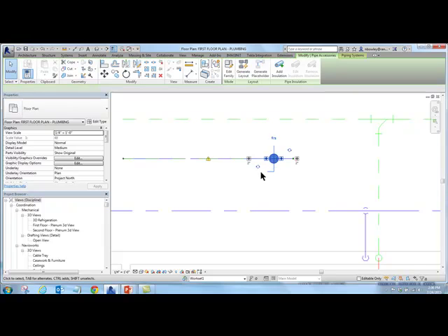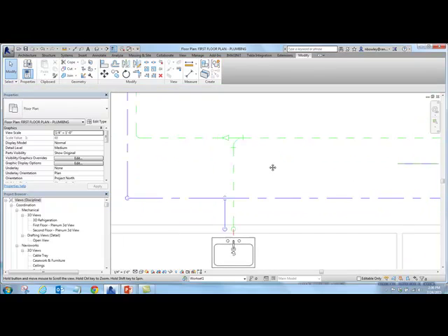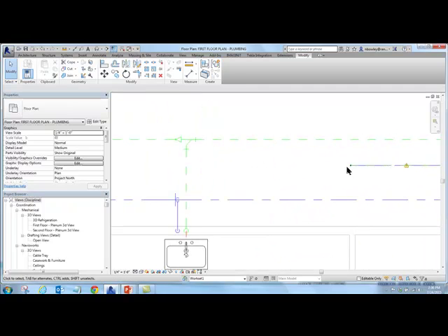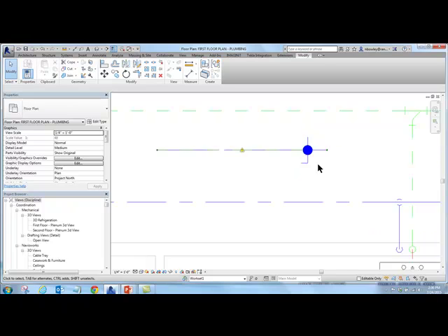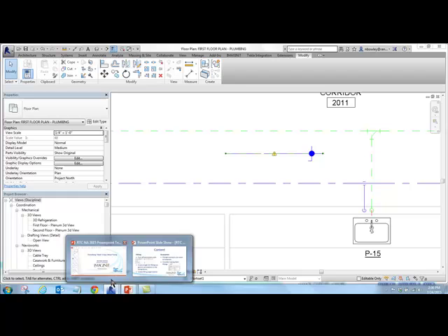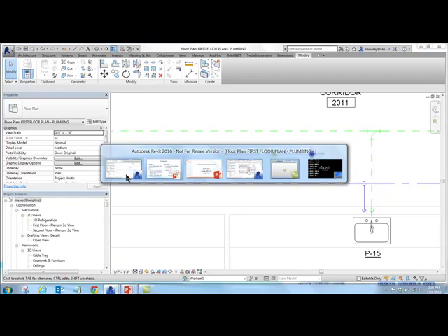So you can turn off the scale of your fittings for the sake of having your half-inch copper elbows still show up like 90s, but your larger pipe still shows up with a radius bend, and you don't have to deal with that kind of problem. So just one recommendation is using the generic annotations inside of the valve family. All right, let me jump back to the PowerPoint.